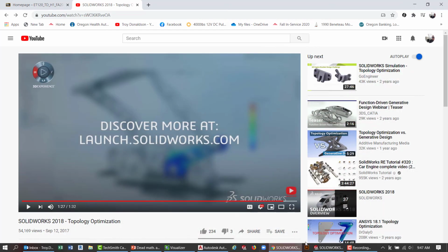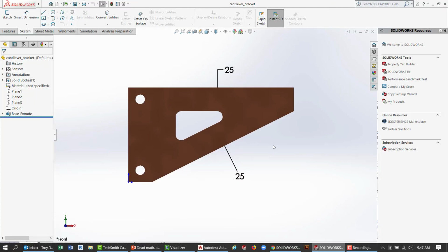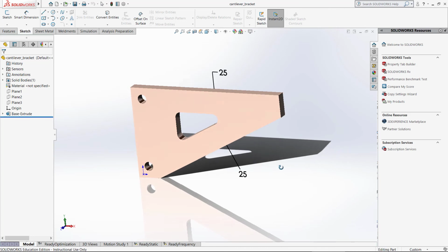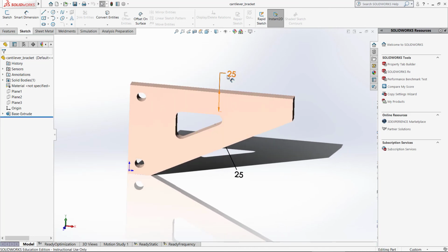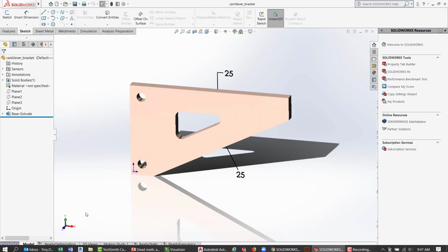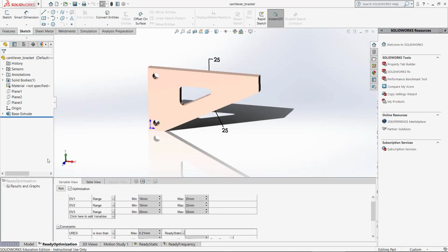All right. I showed you the SolidWorks. Did I show you the SolidWorks? Maybe I didn't. So here it is, where you would set up this part. And you'd load it. So we have some size constraints, and then you add some loads to it. And then it's called topology optimization. This is in SolidWorks, and you can run it.